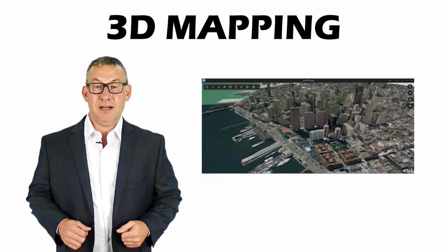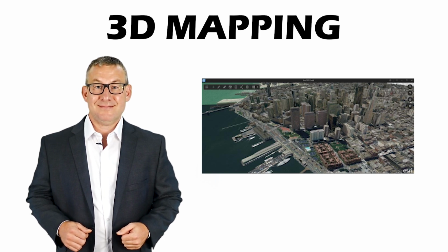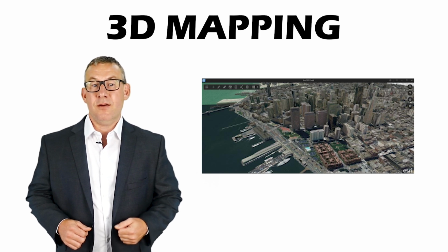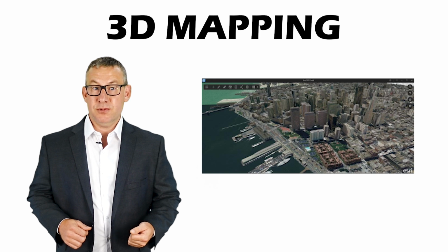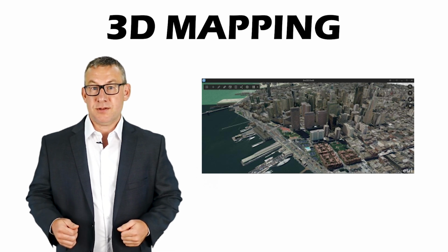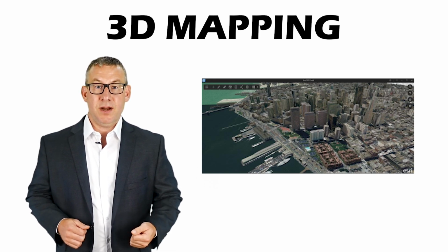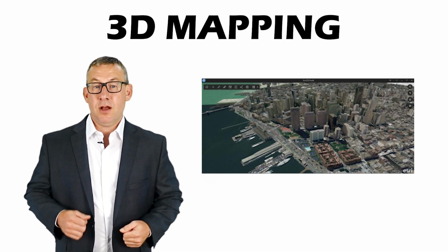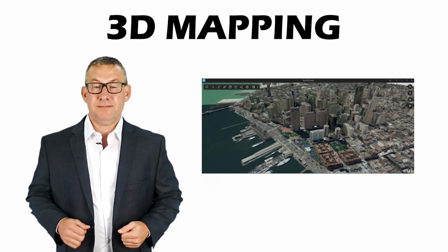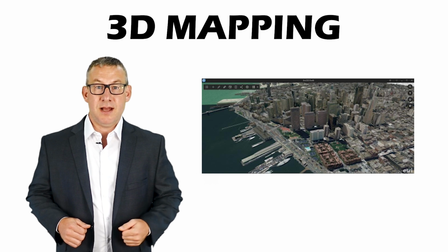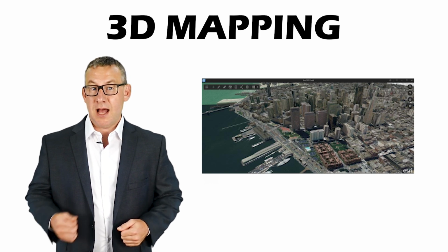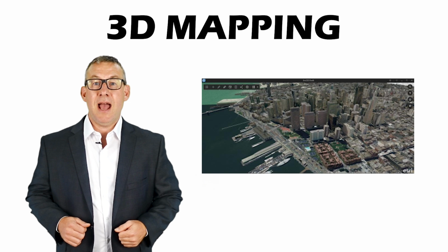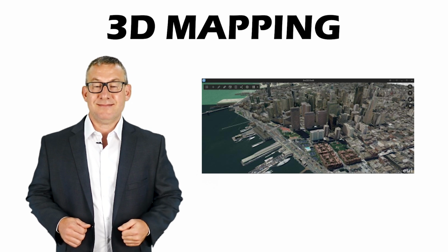(3D GIS data models). 3D GIS data models include vector datasets with z-values, rasters, triangulated irregular networks, multipatch datasets, point cloud datasets, LiDAR data, and digital elevation models.